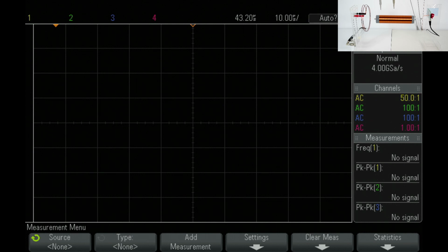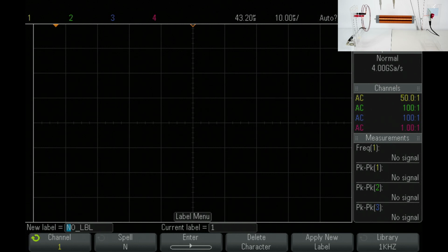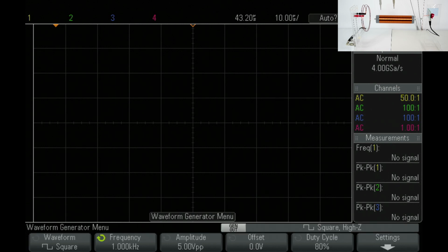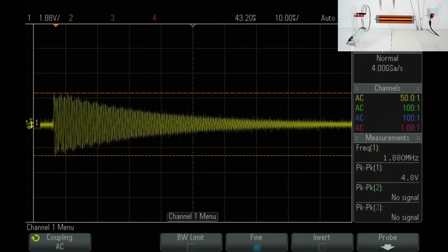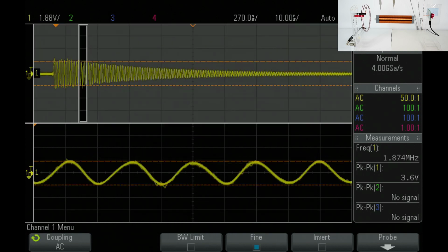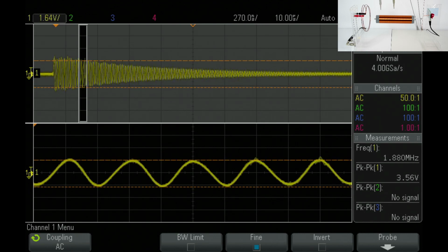So I will now set up the system in order for us to identify the frequency, and we choose a frequency here. I start the wave generator and I start also the amplifier and the signal. So as you can see here, and I zoom in, we have a 1 kilohertz signal. In order to measure accurately, you start with a low frequency.